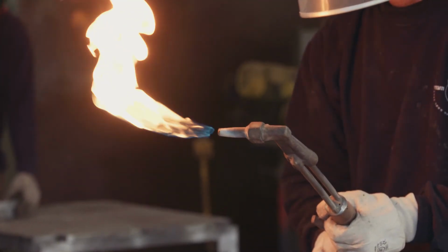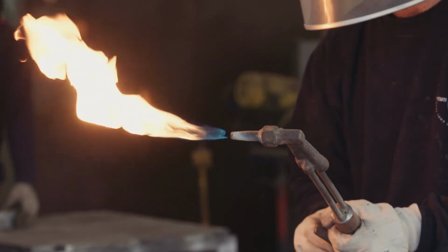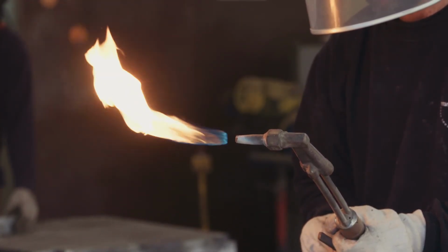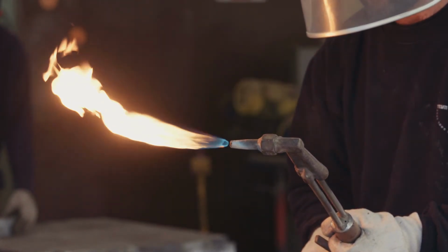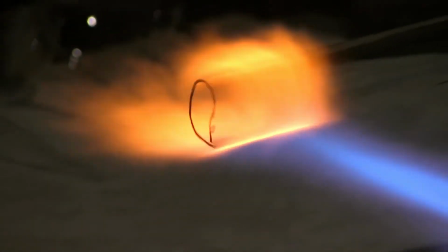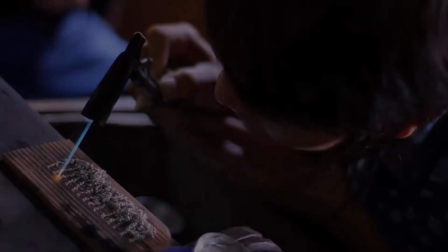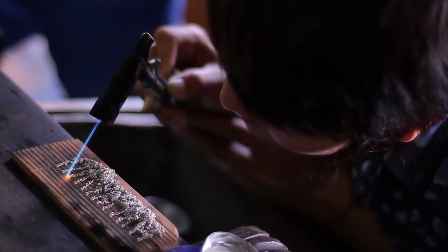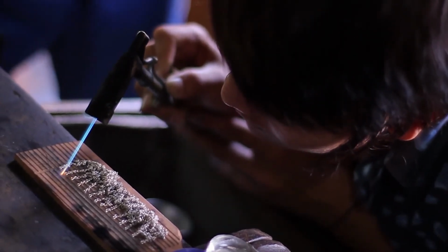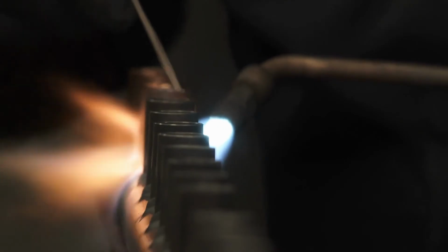So, how does each type of flame affect the metal? Carburizing flames produce iron carbide, which is not recommended for carbon-absorbing materials. You can use this method to weld low-carbon steel. When a carburizing flame is used for welding, the metal under process gets boiled and cannot be seen clearly. Actually, the steel itself is absorbing carbon from the flame, which eventually produces more heat. When the metal gets cold, its properties have drastically changed. Due to the high carbon concentration, it has become brittle, thus it can be cracked easily.